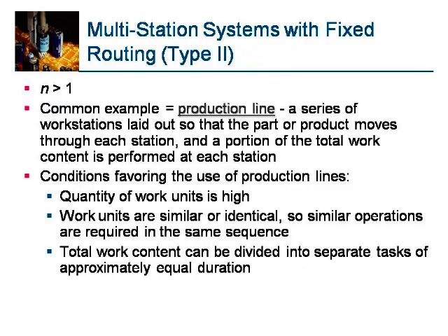Multi-station systems with variable routings, Type 3, N is greater than 1, defined as a group of workstations organized to achieve some special purpose, such as production of a family of parts requiring similar processing operations, assembly of a family of products requiring similar assembly operations, or production of a complete set of components used to assemble one unit of a final product. Typical case is cellular manufacturing.